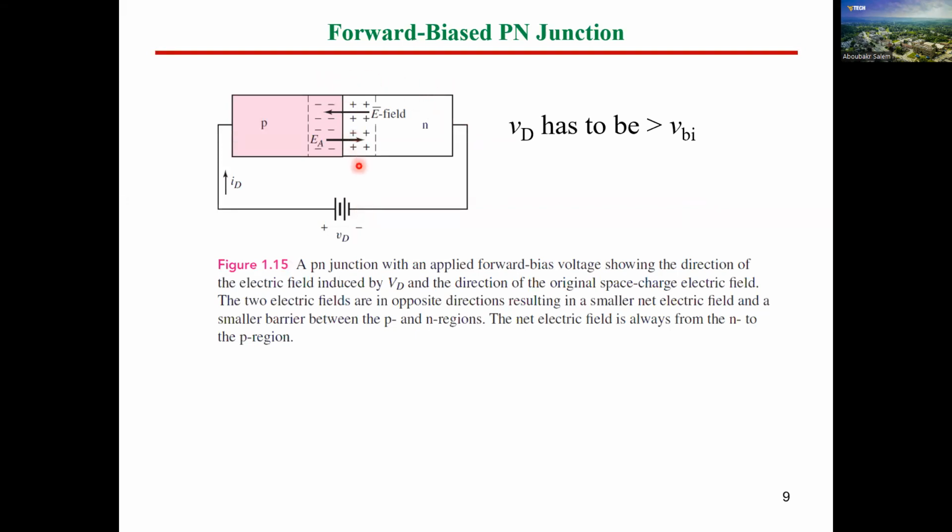So what happens is, if you apply a positive charge or forward bias like that, and if the volt increases over V barrier, this depletion region width will decrease. Decreasing the depletion region width means the resistance of the depletion region is decreasing.